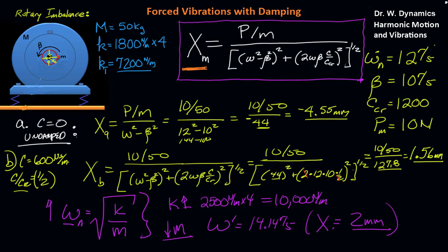And then if we do get a viscous damper, we can cut that down further, so we could get that probably below 1 millimeter. So there's a host of things that you could do as an engineer where you have some control over the natural frequency of the system. We could ask if they could run this at a lower RPM. We could add viscous dampers to it, or we could also come in here and try to balance this thing a little bit and fix the motor. So there's a family of choices that we could have.